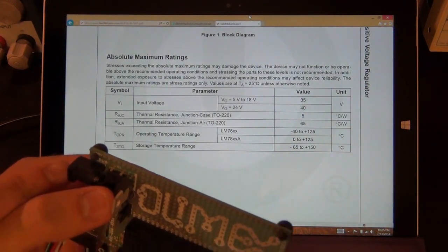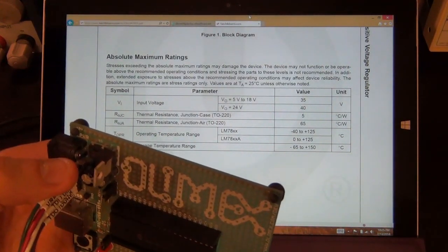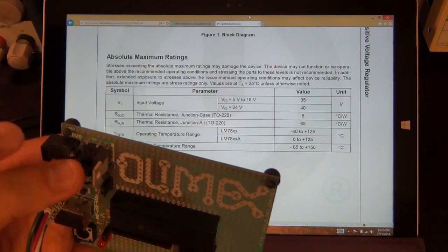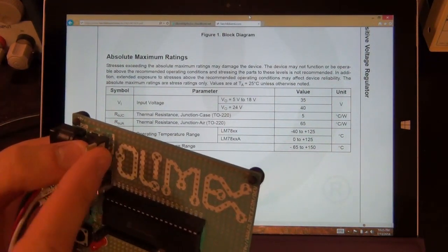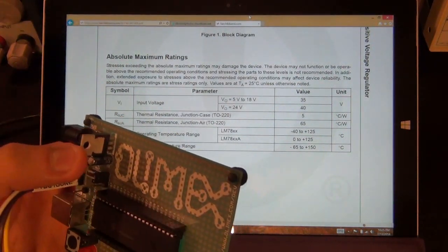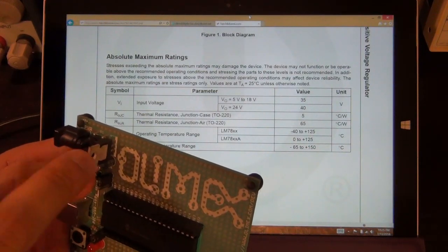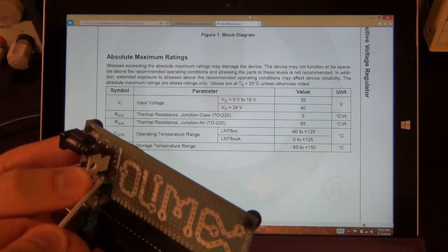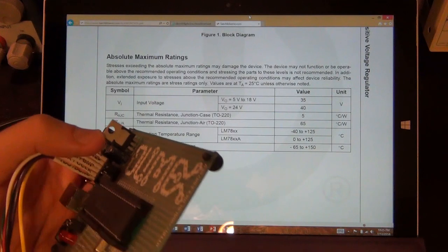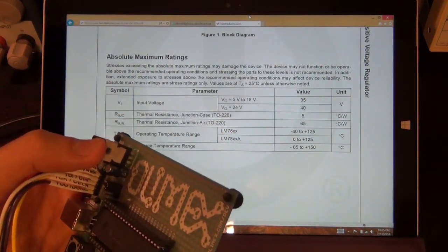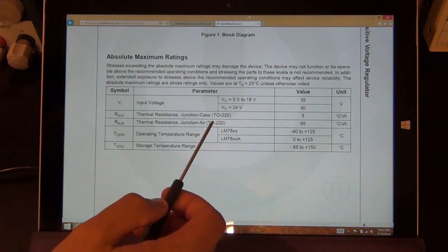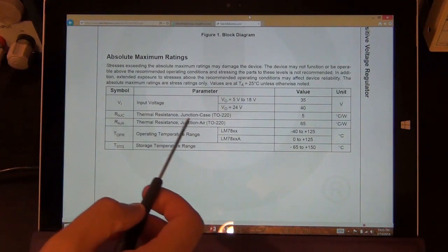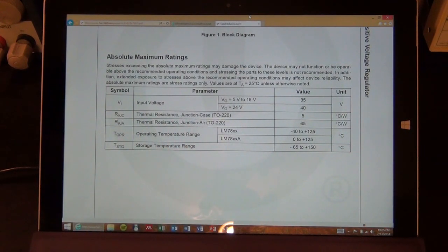Even if I were to give it only 6 volts and get out 7 volts, which I cannot because this is not a low dropout regulator, but let's just say I could, that means I would burn 3.6 watts in it. It would have 1 volt drop across it, 3 amps, so it would be 3.6 watts. Even at 3.6 watts, this regulator without any heat sinks is going to be unusable because the temperature will still exceed the thermal shutdown of the regulator.